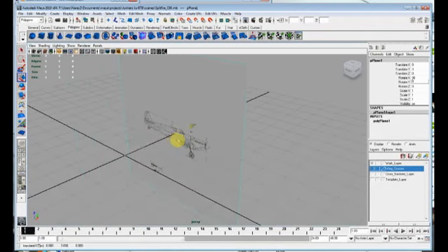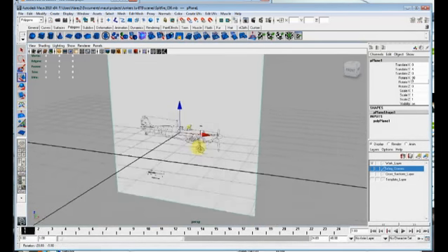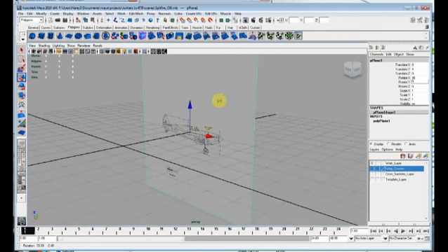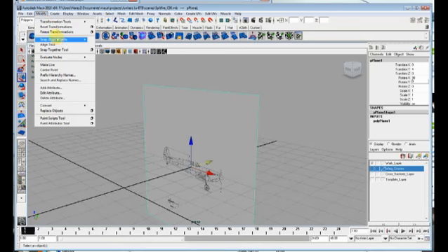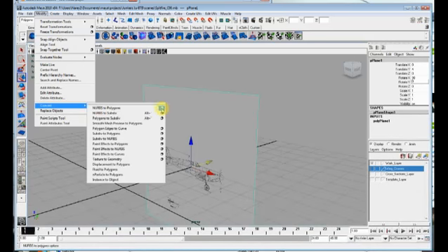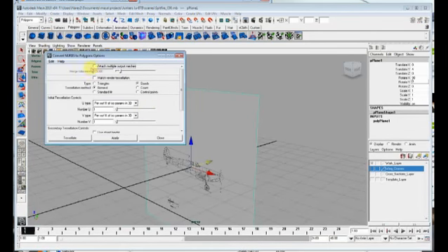So what you do is you convert this from a NURBS to a polygon. And you go up here to modify, and you go to convert, and you go convert NURBS to polygon, and you hit the option box here. And you want to hit these attributes. Tessellation general. You want to tessellate it to quads, or in this case one big quad. U and V are your texture coordinates, and in NURBS they have them automatically. In U, you want per number of surface isoparms in 3D. And V, number of isoparms in 3D. And then you hit tessellate. Apply, close.